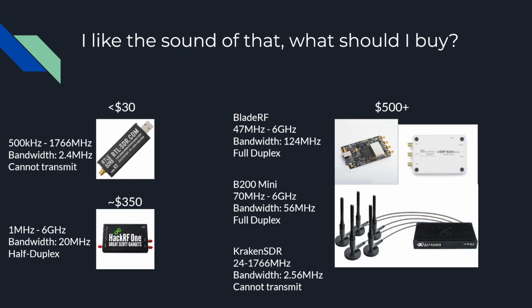If all of those control channels are bigger than 2.4 megahertz, you would probably need multiple RTL SDRs to listen to those different control channels. But that wouldn't be a problem with, say, the HackRF One, where it has that bandwidth of 20 megahertz. It could capture all those control channels and even possibly listen to the data channels that are being sent on trunked radio systems. So bandwidth is something that I put in here as a consideration.